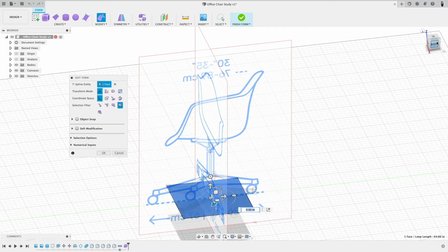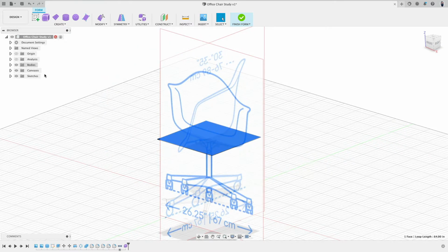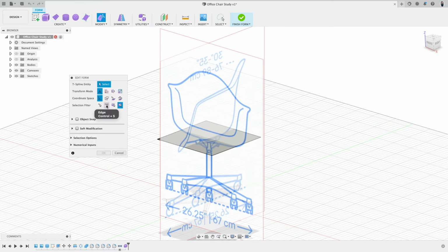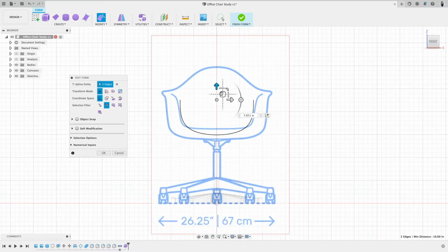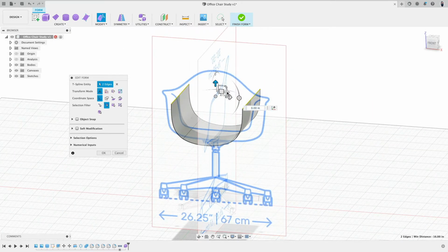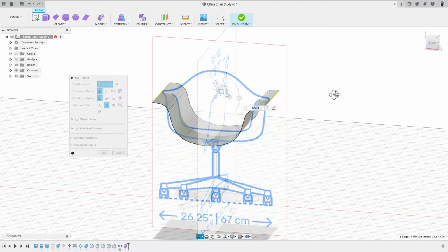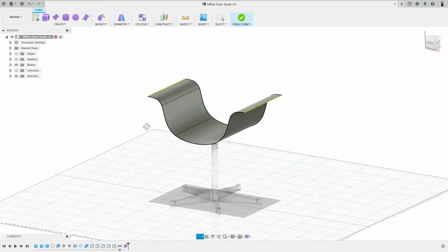Then this face, I will move up, maybe to where I want it to be. There we are. Okay. Now the interesting steps. Modify, edge select. I will select this edge and this edge, hold the Alt key and then drag this one up till, for example, we reach this part. Now the next step, hold the Alt key and then you see here, I click on this sideward scale and we scale this part out. Click OK. Turn canvas off.